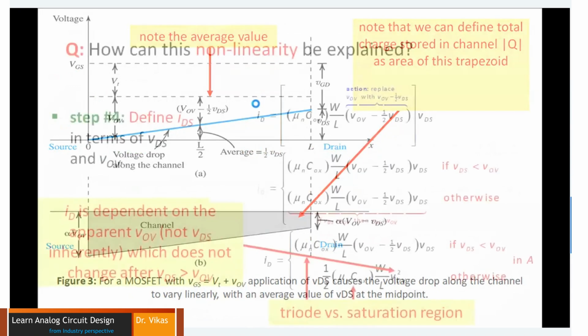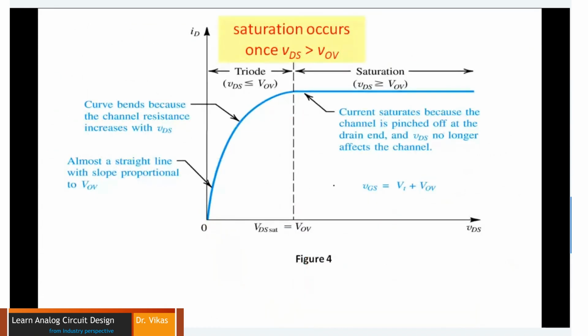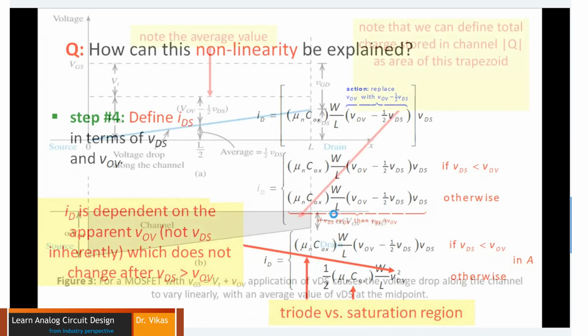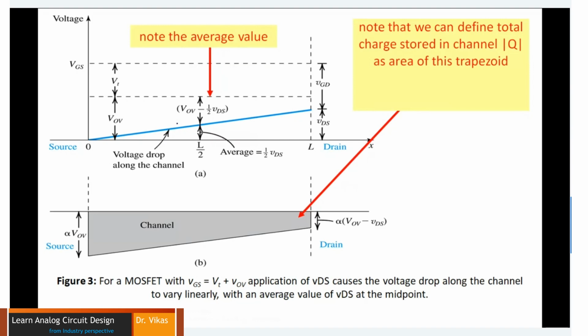Now, before I reach this particular equation where you see the drain current equation, there are two current equations I have written over here. So let's look at my entire channel construction and its voltage distribution within the channel, how exactly it looks. Like I told, when a channel is created and my MOSFET enters the saturation region, there is a pinch off that happens.